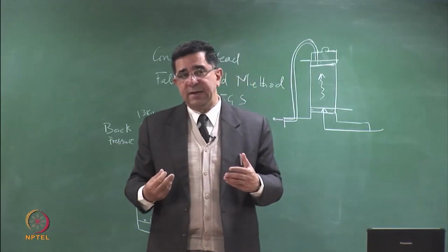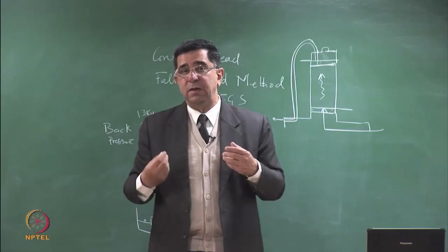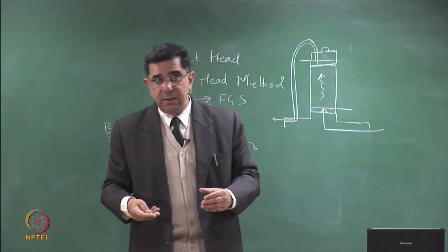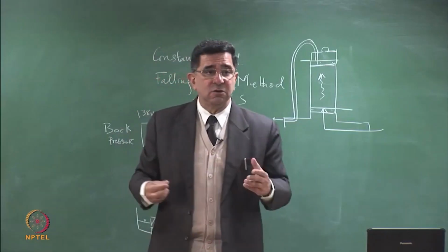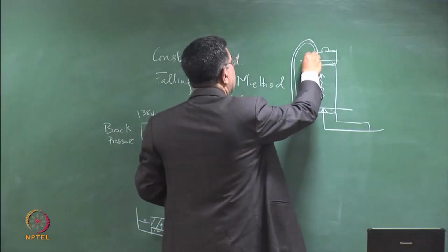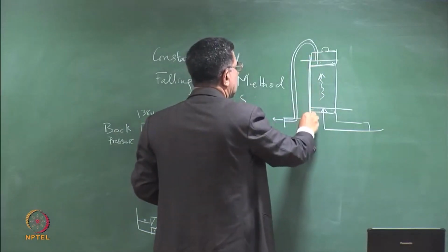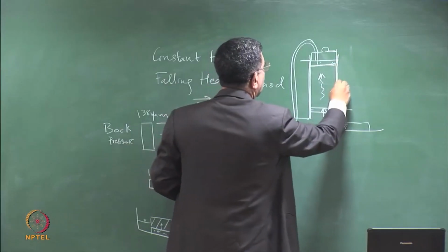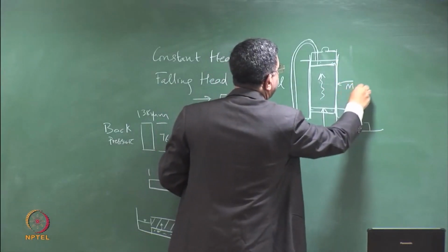So the concept is identical. You can read up more about this, but why is it called flexible wall? Because it has a rubber membrane around it. It's not a rigid wall like a consolidation ring. So you have a membrane around it, and that's the flexible wall. The membrane prevents side wall leakage.